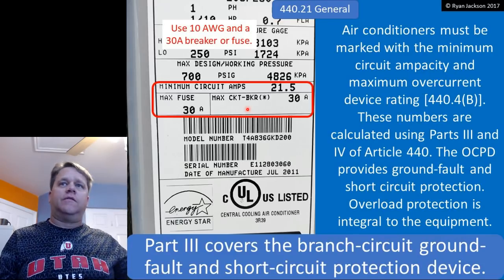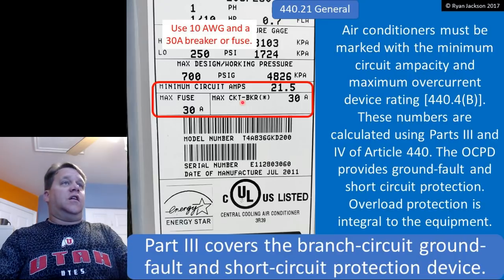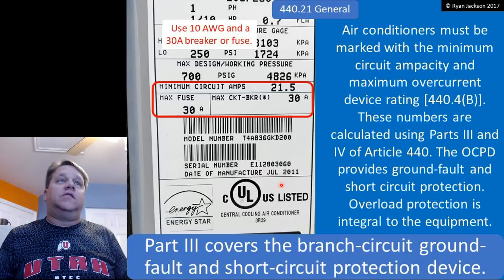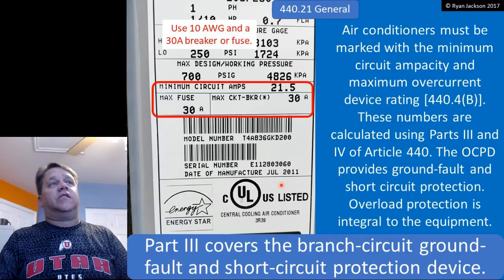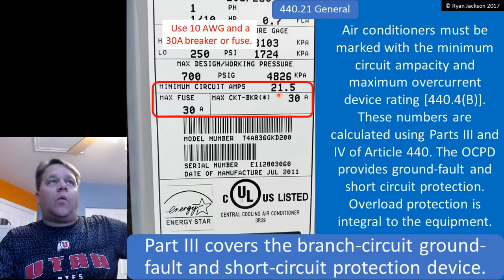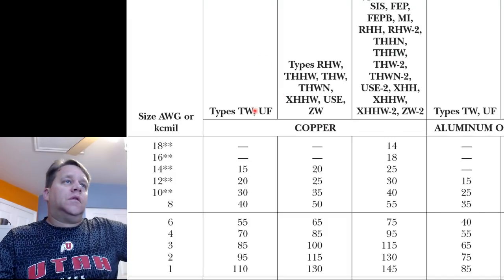That's 334.80. Or we're just going to say, look, this isn't marked with its terminal ratings, and 110.14(C)(1) says that if it's not marked, you have to use the 60-degree column. So let's use the 60-degree column. I need a wire that can carry 21 amps. 60-degree column, 12 gauge isn't going to do it.